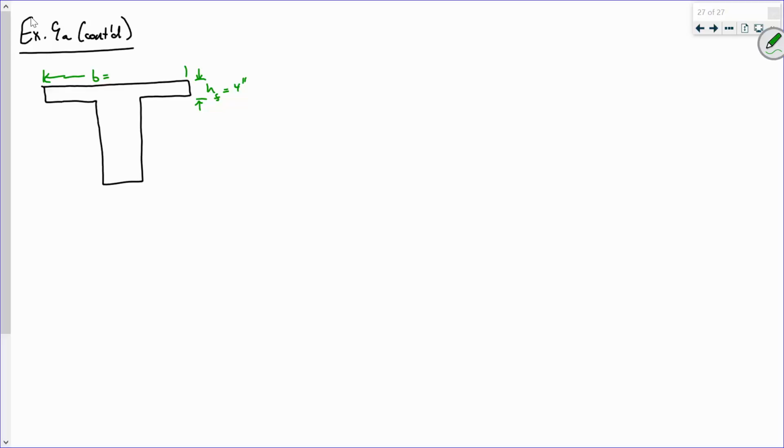It might not have equaled s. It could have equaled bw plus 16hf. You see what I mean? That's why I'm calling it b. I see where you're getting at, but I want to be diligent on my notation. And this was what? 60. Okay. All right, so let's be clear on something. What is the area of the flange? Just keep it simple. There you go, b times hf. Yep, which is 60 inches times 4 inches, which is 240 square inches, right?